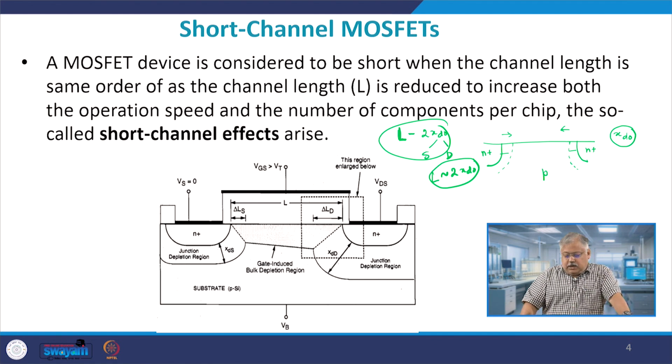One is obviously in design there are 3 components, which are power, performance and area. This is a very important parameter which we use in a design problem, be it analog or mixed signal design. So, you want to reduce the area. Reduction in area can take place if you are able to scale down the dimensions of the devices. And one way to scale down the dimension of the device is to lower the channel length drastically. Once you lower the channel length drastically, the effective area reduces, and therefore, the silicon utilization reduces, and you can pack in more number of devices per unit area.